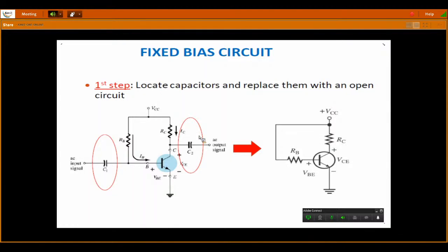So with that we get a total of 2 Vm signal at the output with a zero reference axis. So in order to block the DC signals present at the output, we have coupled C2.